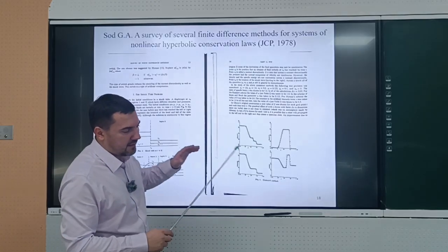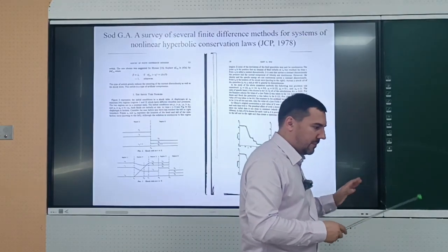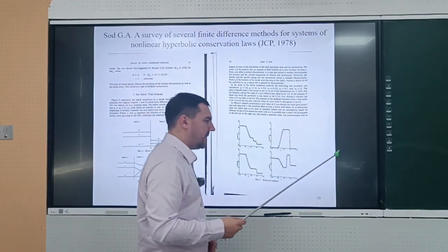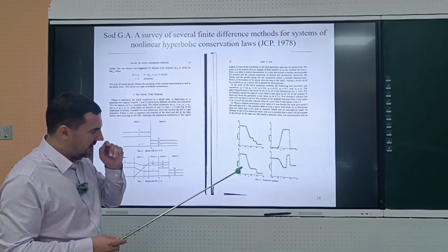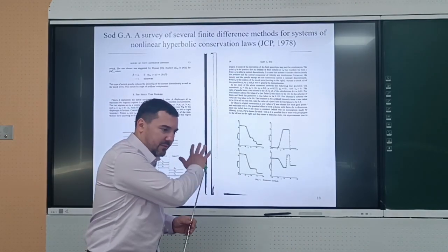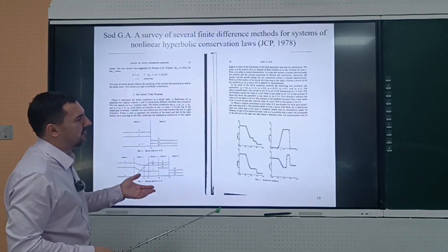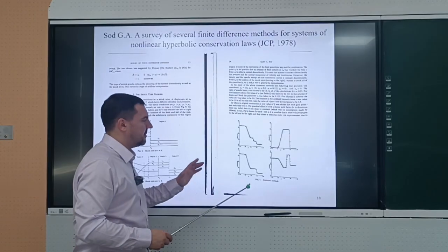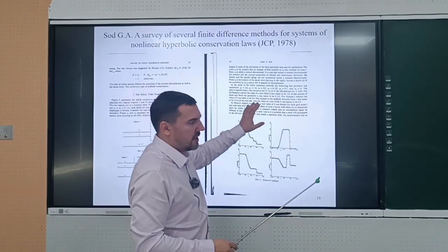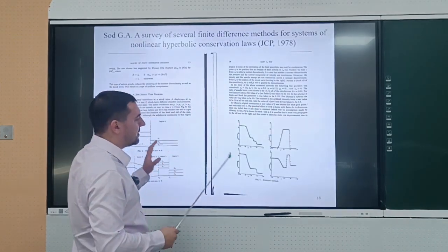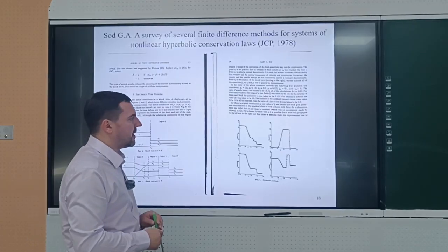After that, and till now, if you try to publish a paper and introduce some numerical method, maybe the first or second verification or validation test should be the solution of this Sod shock tube problem. Actually, this is a mild test, so the gaps in the pressure are not huge, just 10 times. So that's not a very demanding test case for a numerical method.